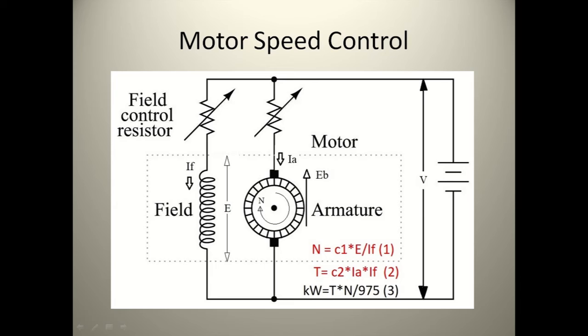DC motor control. Scheme showing armature voltage control and field current control by simple variable resistances. In actual practice, electronic converters such as mercury arc converters, thyristor converters or IGBT-based converters are used nowadays.